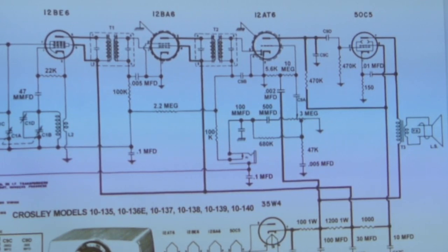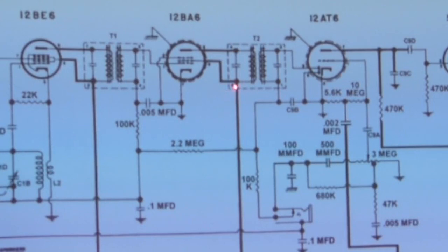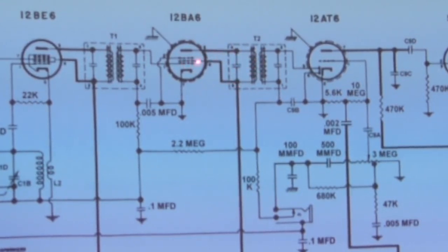Capacitor. Which capacitor? There's no capacitors in there. That one has a cap in the IF transformer. Yeah, no, you don't know that this capacitor has failed yet. All you know is that this stage is not working. Even if the capacitor failed, you would get a signal out here of some sort. You would find something. You wouldn't be totally dead. So, you put in a good tube, and it's not working yet. What else could be wrong?